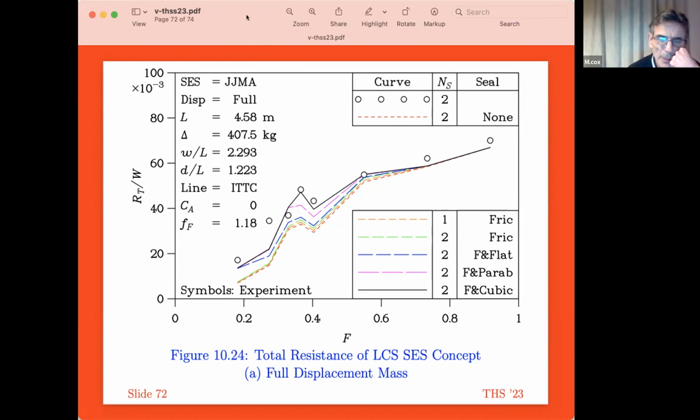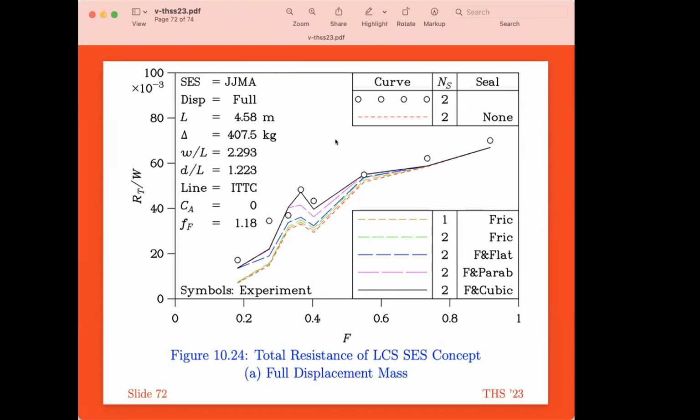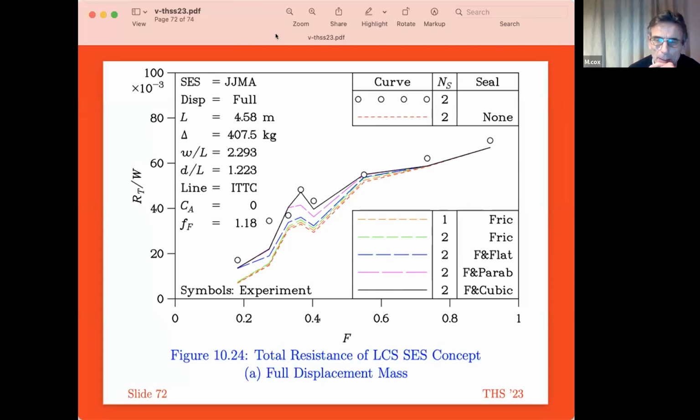I know in some of your previous work, you've looked at wave-making cushion perimeters and whether they're hard-edged. Yes, that's right. That goes back longer than I care to imagine, almost 60 years now. Or whether the transition from the cushion pressure to the external pressure on the water is a gradual one. How do you think this theory with your parabolic theory ties into that? Because on an amphibious craft, you've obviously got this effect all the way around, haven't you?